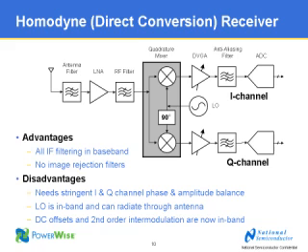So a little bit more detail on the direct conversion receiver. As I mentioned, the advantage is that it's less complex. You actually have really no IF filtering. Everything's done in baseband. So you have baseband filtering, which is generally easier to do than IF filtering. You don't have an image to deal with because you're not using an IF. You don't have an IF conversion stage. So you directly go into baseband, and no image rejection filters are needed. The disadvantage is that, as you can see now, at the mixer, you have two particular paths.